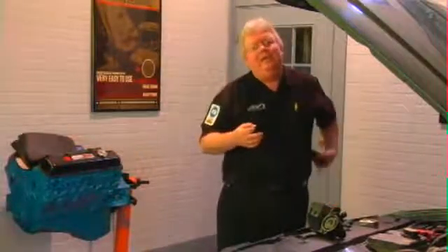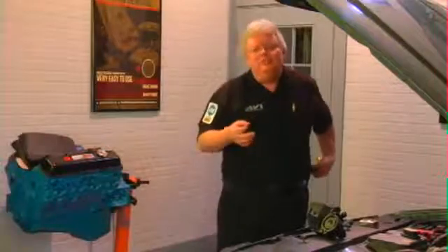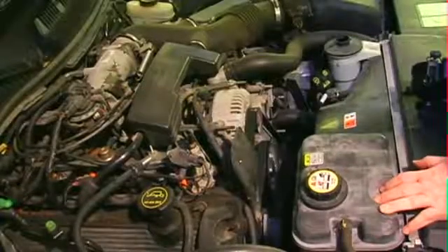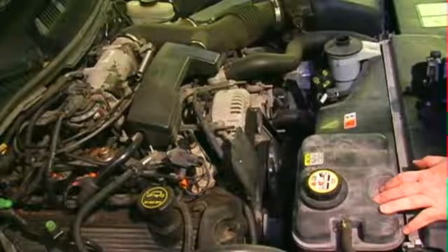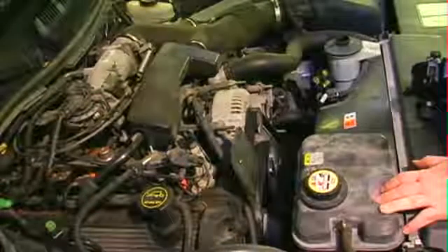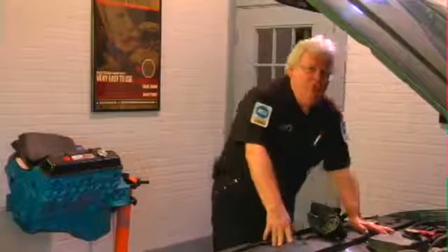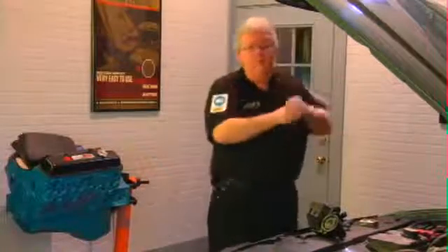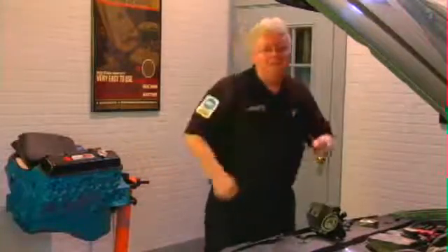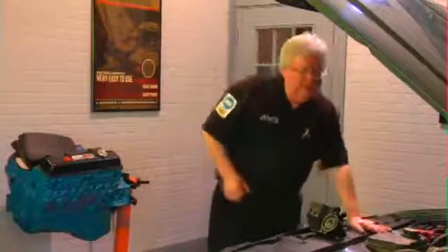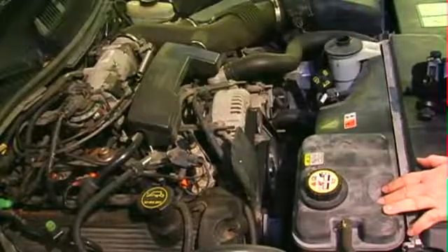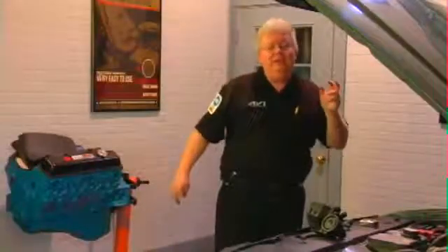So what you want to do in that case is you want to follow the manufacturer's procedure, which on some cars may involve a plunger plug that fits tightly into the power steering reservoir opening, the filler neck, and it puts the system with a hand pump under a vacuum. And you run the engine and you move the steering wheel from lock to lock, and again, not lingering at full lock more than a second or two. You do that about 10 times. Then you shut the engine off. Then you take the vacuum away. Make sure you top the fluid off. Repeat that procedure. And that should get the air out of the system.